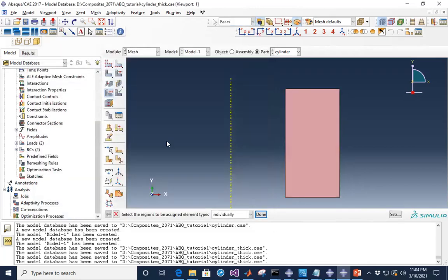So if I hit OK now, all that's left to do is to actually create the different elements. So Abaqus has this simple option, right here, it says mesh part. So that's what we want to do next. We want to create the mesh. So I'm going to click on this mesh part. Then there's this instruction which asks me if it's okay to mesh the part.